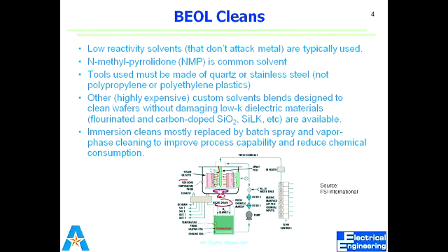The faster it cleans, or we'll talk about later when we'll be talking about the dry etching process. In the etch process, you will come to know what is the effect of adding oxygen or the effect of adding fluorine to any chemical composition and how it will be affecting the etching process. Because cleaning is actually a very slow rate etching.